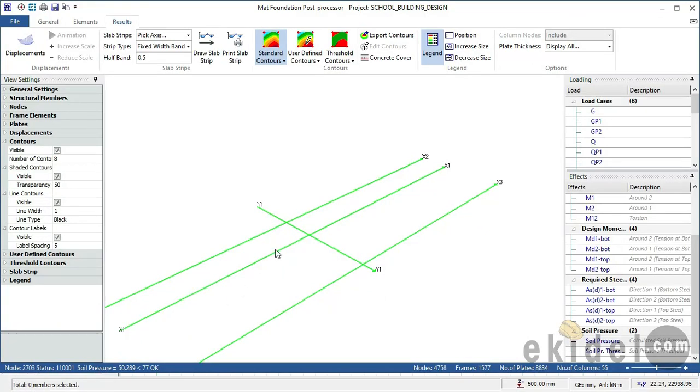I say again, don't click anywhere, because once you click anywhere, it will make your system slow or hang, and most times the software can just shut down. And if the software shuts down at this very stage, everything you have done is lost, because we have not saved anything, and you cannot save on this place. If you want to save here, it will not save the main Prota software of your model. So you can now see that we are on strip 1.